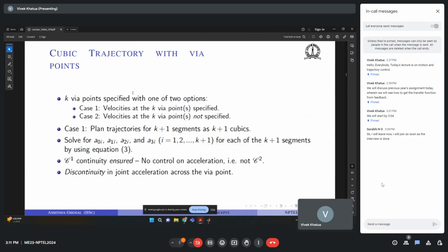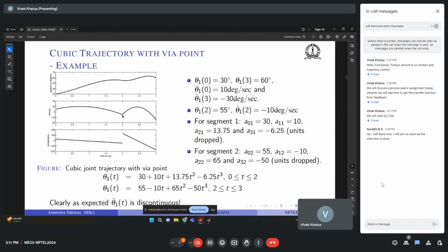That is, when we say that it has to follow a certain velocity at a certain time, you get a kink there, and that is where you have your jump in acceleration. And this is still fine. We can give a ramp, and we can eventually get over it. But anyway, we would want to avoid these kinds of discontinuities. What this means is that the motor was decelerating, now suddenly it has to accelerate to this point, and then it has to decelerate from there.